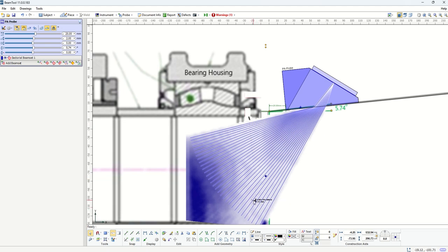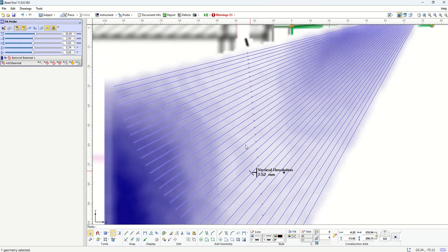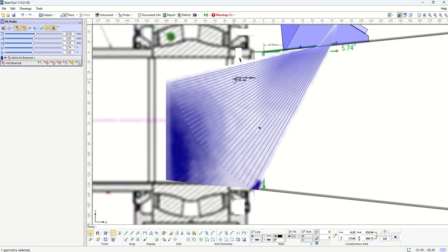So what this tells me is that if I choose this sectorial beam set and choose the focusing right here with all the aperture, my focusing quality is such that I can remain sensitive to positional variation of this crack for plus or minus 15 millimeter. And that tells me that this can be a good technique to use here.